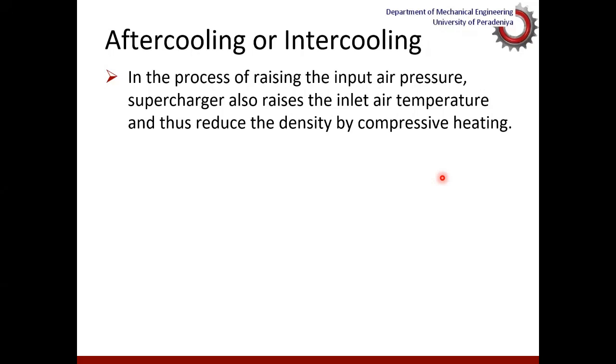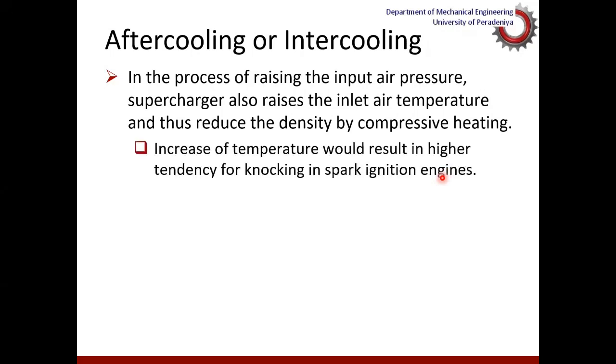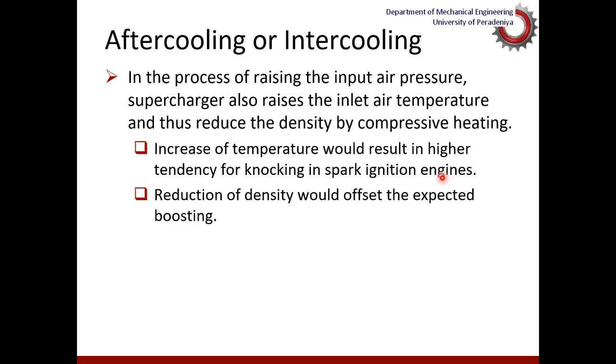And there are advantages and disadvantages to that. In spark ignition engines, this becomes a disadvantage, because the higher temperature at the beginning of combustion would lead to auto ignition of the end gases, a phenomenon known as knocking, which we looked at earlier. On the other hand, generally an increase in temperature would reduce the density, and that will offset the expected boosting.